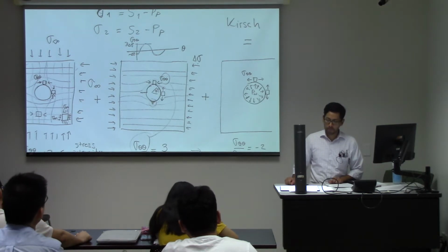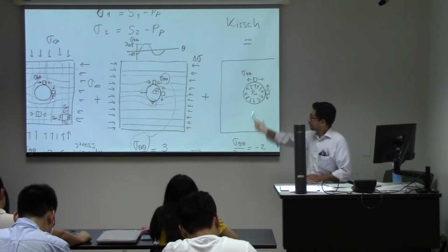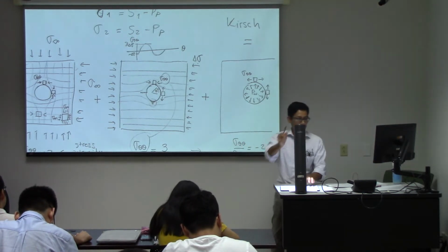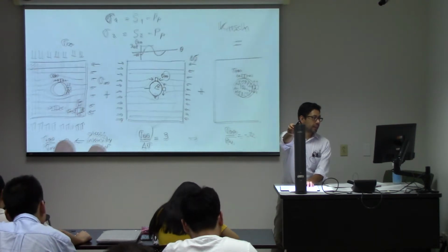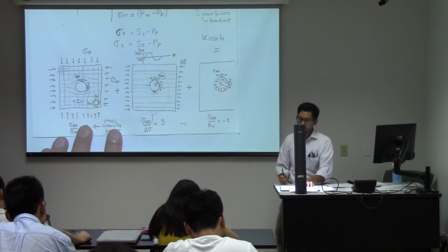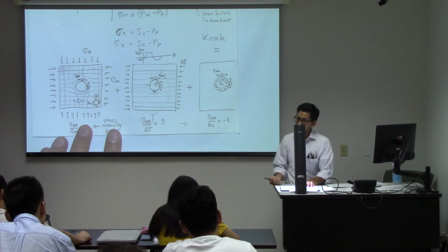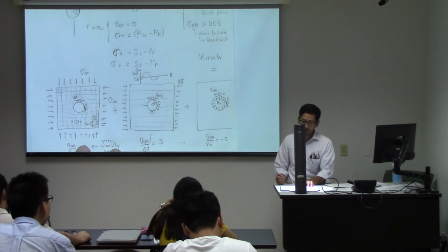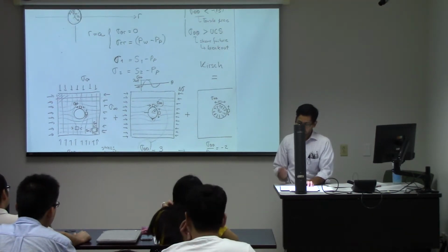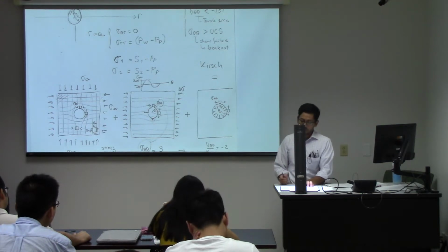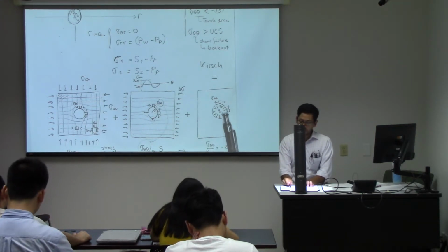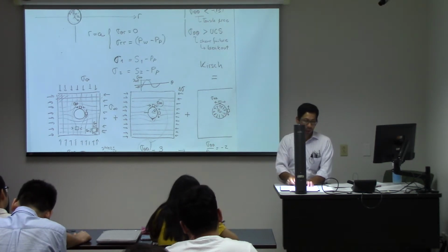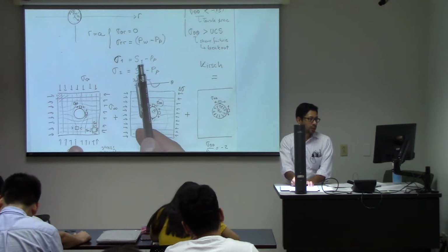Yes. Okay, but here, we could have either compression or tension. Yes? I'm sorry. The solution does not consider pore pressure around the wellbore, but actually there is a rigorous solution of poroelasticity for the wellbore. If you were to consider pore pressure, this value inside here should be PW minus pore pressure, and all your stresses should be S1 minus pore pressure.